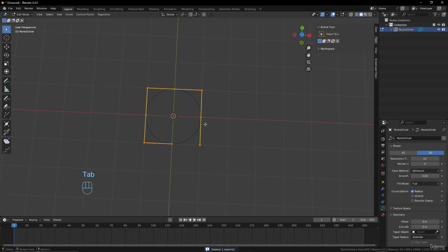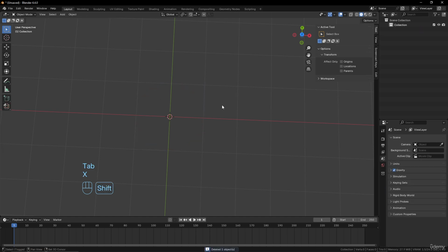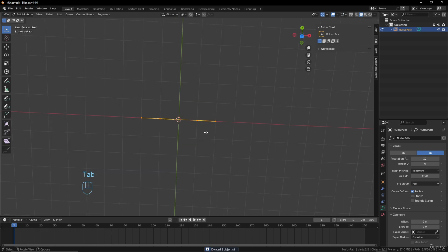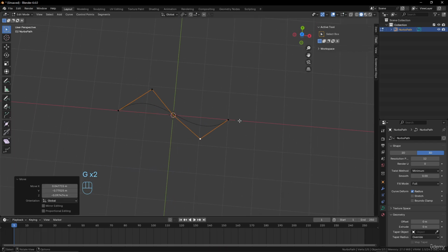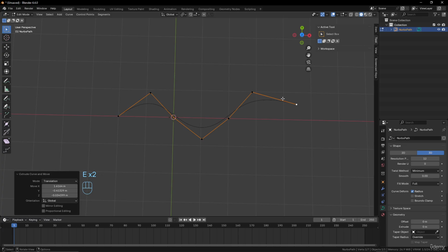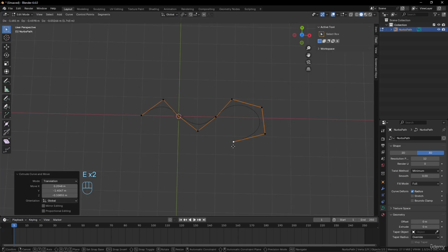The NURBS circle exists as well, so with dots and not handles. And you have the paths that I really like to play with, and we will have a full video on this, so you can really make a better shape, because the curve follows the last extrusion compared to the NURBS. So yeah, it's a little better to create nice shapes.